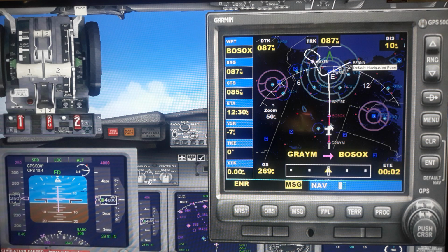So many things. But let us now from here we will go 150. This is 150 heading. This is 330. So 150 plus 180 is 330. So this is 150. I'll come here. Then I will take a heading of what we decided, 60. Then by the time I reach here, I will change the heading to 10. Then I will put the approach button. From that point, it will take off. The plane will take the center line and come and land.